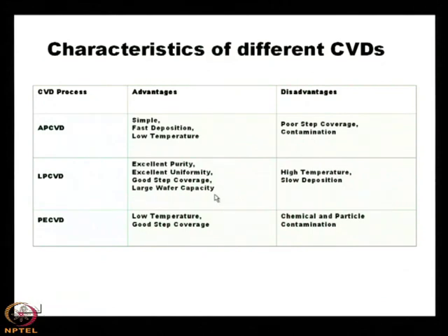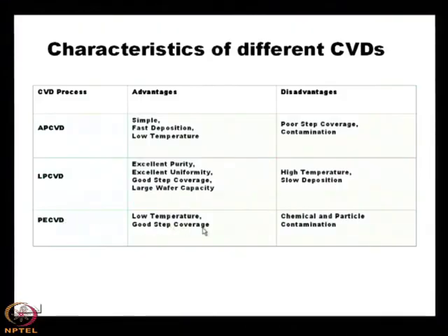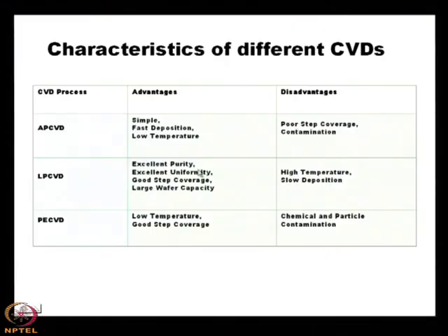Okay. Now, 25 wafers can be used in an LPCVD chamber, but in a PECVD chamber only 4 wafers you can use, because the efficiency is less in case of PECVD. Another important thing is that using PECVD, both sides of the wafer cannot be covered with film. In LPCVD both sides can be covered, but in PECVD only one side of the wafer.